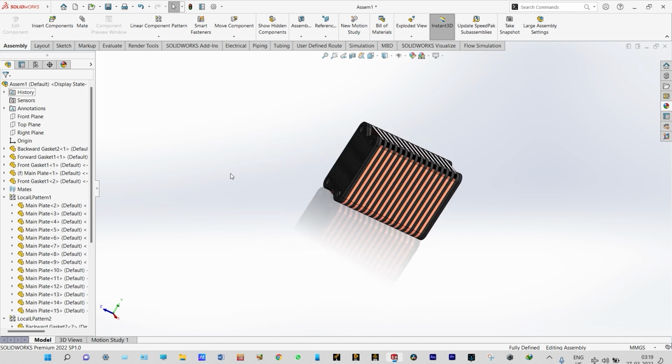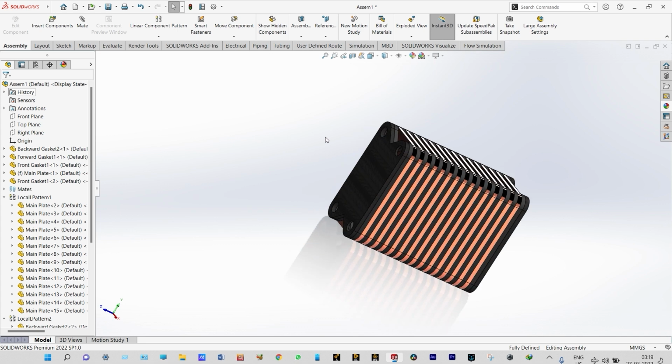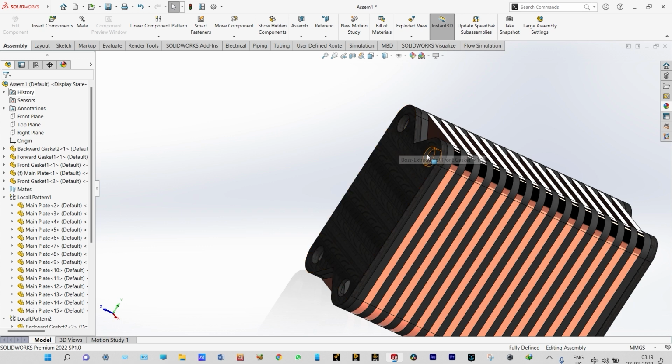What we have done is, in this plate heat exchanger, we'll be providing two different types of fluids. Maybe we'll consider this one water at different temperatures. From this top opening, we'll provide hot water at a temperature of 100 degrees centigrade. It will flow in the forward direction. At the same time, it will flow sidewise in the left hand side direction.